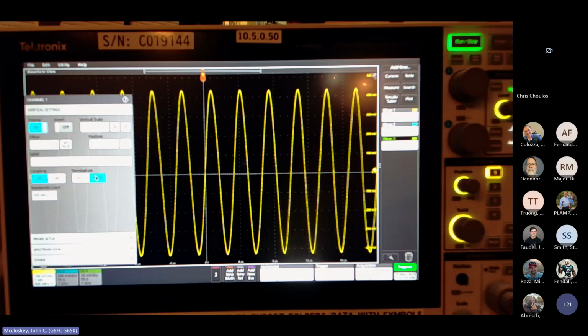So I'll show you the schematic here again when we're done, but it gets back to, you have a 50 ohm source impedance now, because at the higher frequencies, certainly above about 1 megahertz, you're on the flat part of the insertion loss curve, where the physical loss of the probe is not very significant. And then you're looking at the 50 ohm source impedance from your signal generator going into the full 100 ohm load of the fixture.